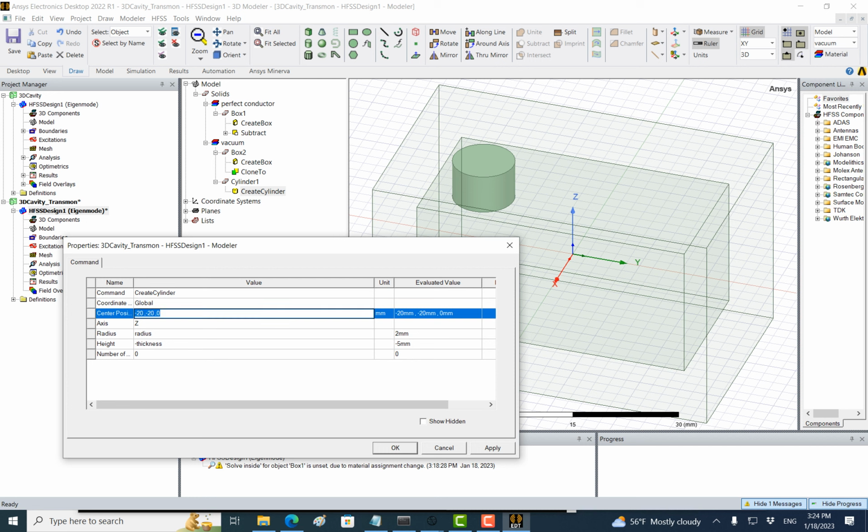But where is the location? Now this location, of course, for the x, I'm going to have 0. I'm going to make it at the center, right? But for the y, where should I put it? Maybe I will put it at, let's say, negative y maximum, remember, minus the thickness. That would be at this region, right? And then let me just call it an offset, shift it, right? For example, I can put it by, let's say, 10 millimeter, okay? But you will ask me for the offset later, right?